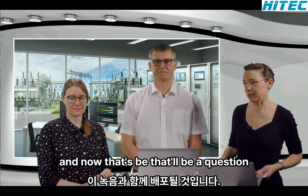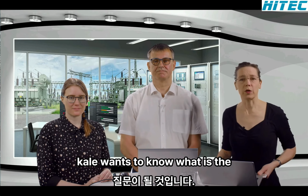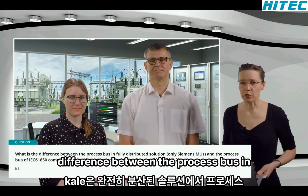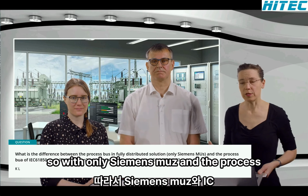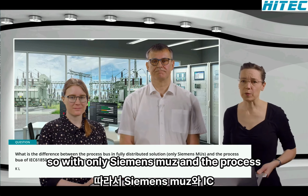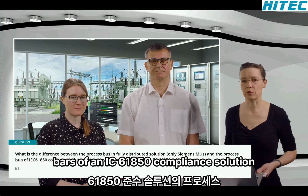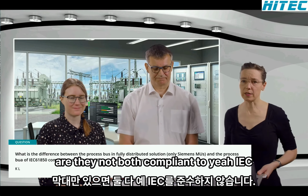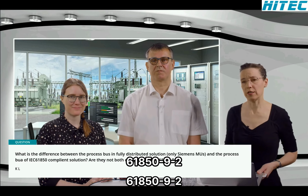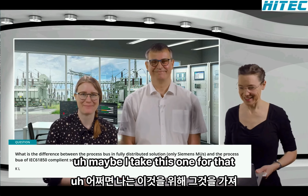And now that'll be a question to one of you. Kale wants to know, what is the difference between the process bus in a fully distributed solution, so with only Siemens MUs, and the process bus of an IEC 61850 compliant solution? Are they not both compliant to IEC 61850-9-2? Maybe I take this one for a start.